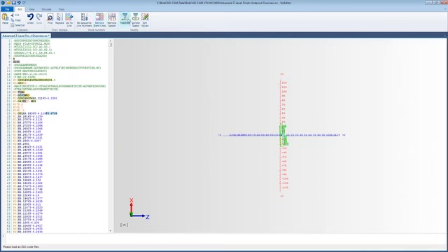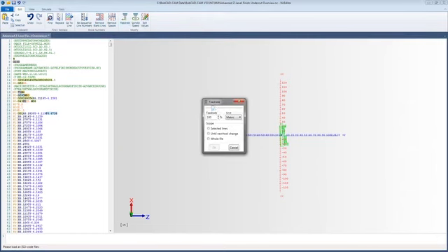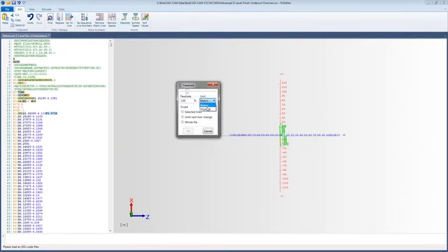You can also change the feed rate, which is kind of cool. You can go in and do a certain unit. You can say, I want to do imperial. Let's go 200% the feed rate. So I'll go right there. And I can say, do that to the whole file and just hit OK. And so we'll see right there, we're at 13.3476. I didn't look at it before, so let's hit OK again, and it's going to double that now to 26. So you can actually change your feed rates right there.